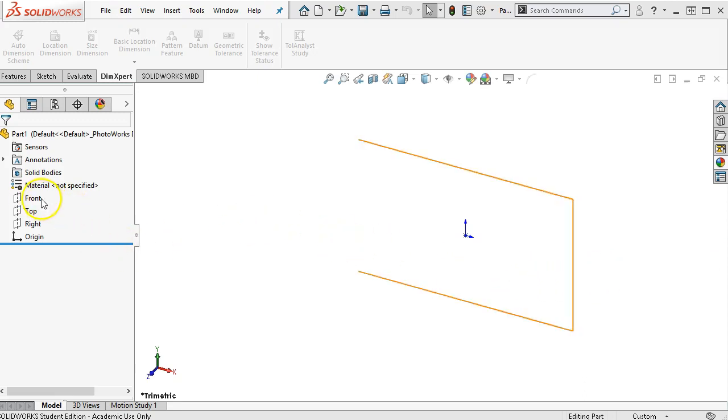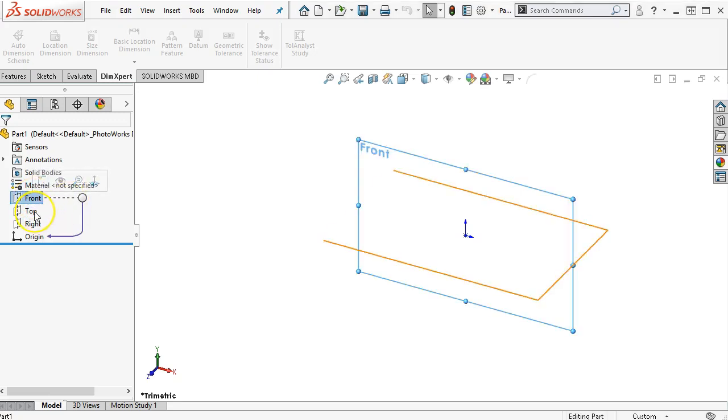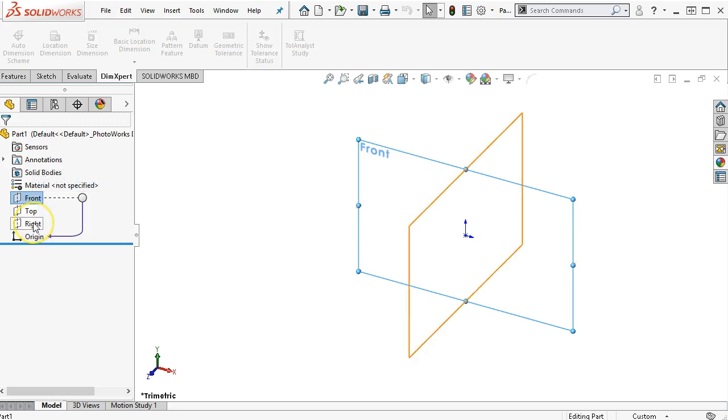All right, so from the front plane, if I highlight and just hover over top, it's going to highlight in orange. If I select it like the front plane, it's going to show up in blue. And as we drag over each of those items, the origin shows up as a point. The origin is the intersection of those three planes, and that is defining our location, giving us a starting point in this 3D environment and in the universe.